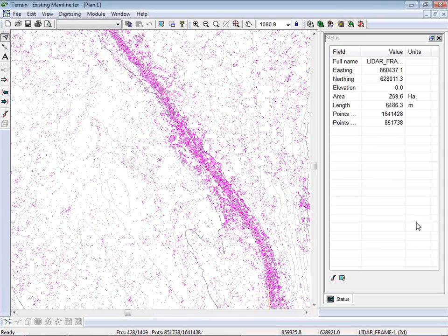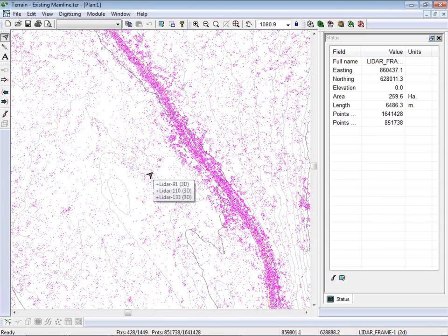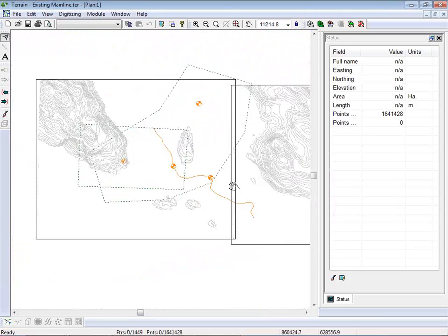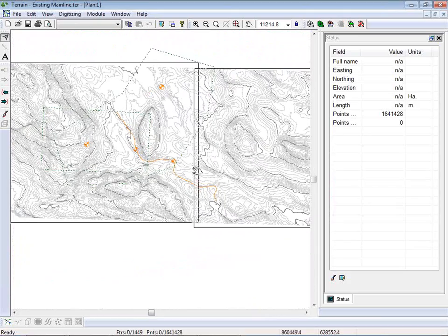Now the nice thing about the method that I use, I don't need to look at these LiDAR points anymore, so I'll just deselect them and they'll disappear. The nice thing about using the selection method that gives you all the data but thinned where you're not using it is that you get contours everywhere. So you can see the context.